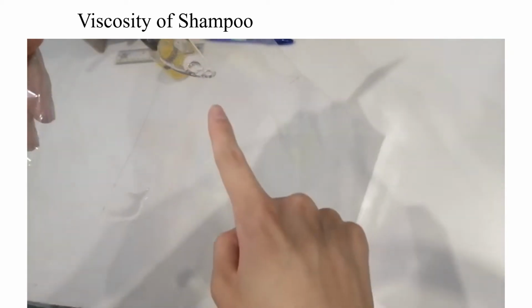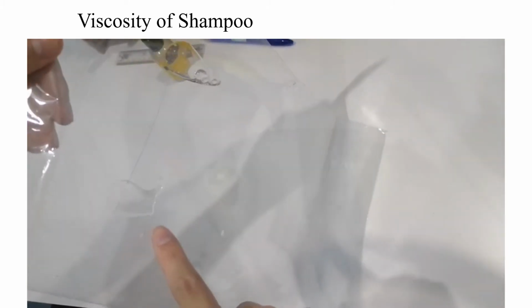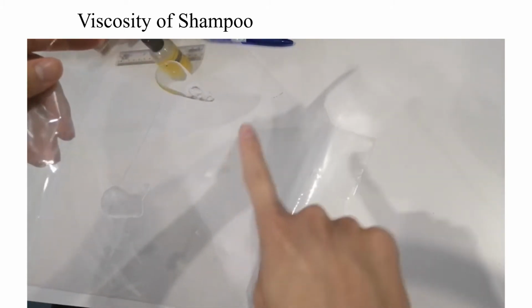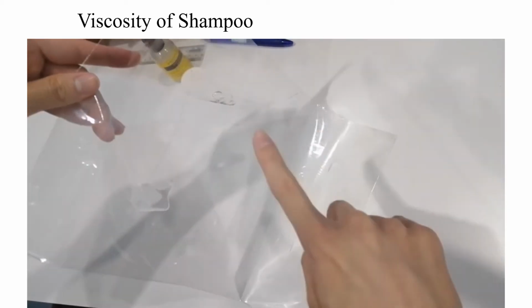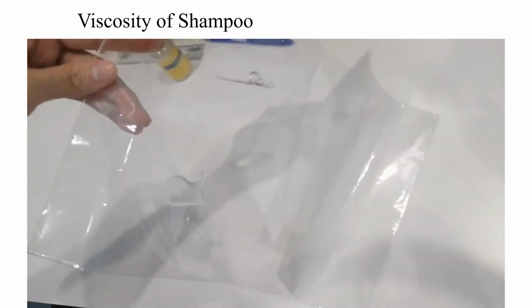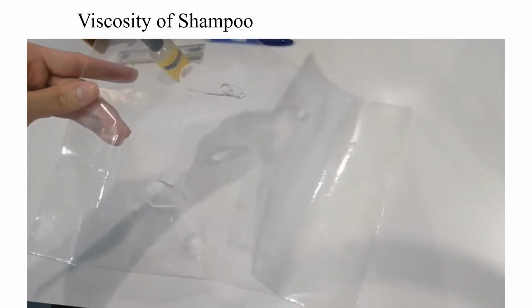As you can see, the one being shaken is flowing faster compared to the one not being shaken. And as expected from what I said in the beginning, the one being shaken will flow faster than the other one. So here we can see a shear thinning process of a shampoo.